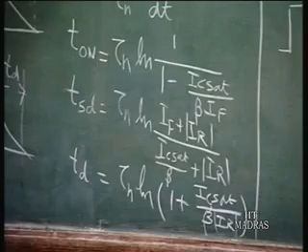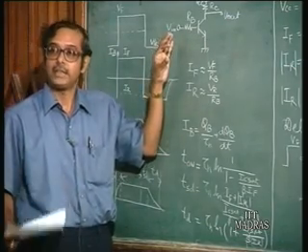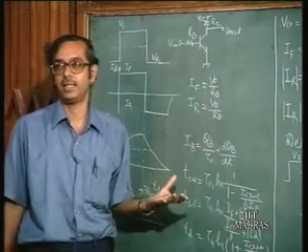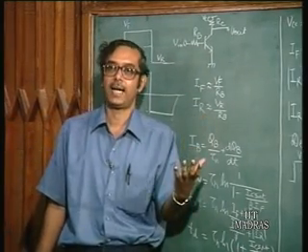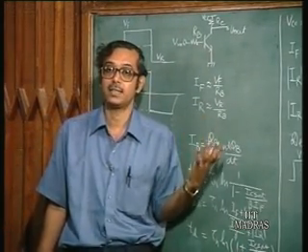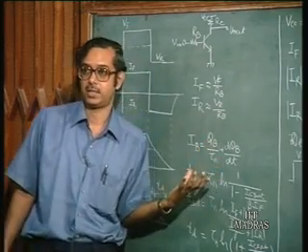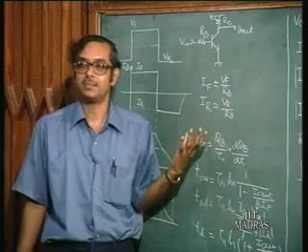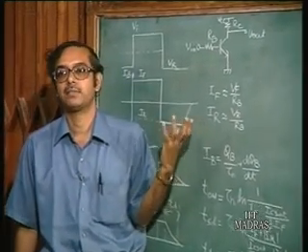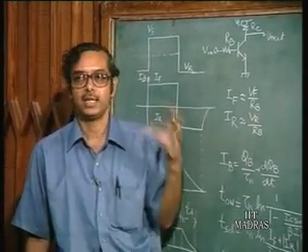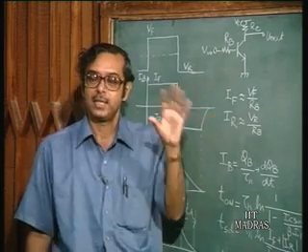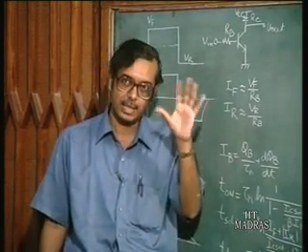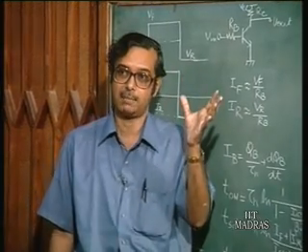So in this circuit, if you change the values of all resistances, increase or decrease, by the same factor, the delays due to the stored charge component do not change. That is because, if you consider them as some capacitance, the RC time constant, the diffusion time constant, the RC time constant due to the diffusion capacitance.